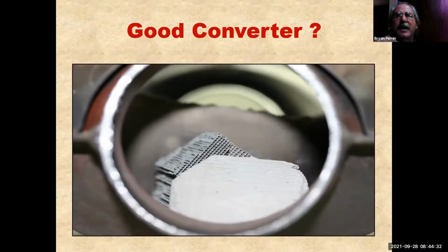And so when someone says, I tested something, that's why I routinely go, how did you test it? Well, I tested it. No. How did you test it? What methodology? How did you determine this? So when someone says, well, I tested it, it's good. Okay, how did you test it? Can the test you took only tell you if it's bad, like an ohm meter test? An ohm meter test can't tell me if something's good. It can only tell me if the windings are bad, not if they're good. There's a lot of tests like that in automotive that can't tell me if something's good, but unfortunately we're fooled into believing that if it passes the test, it must be good. No, it just hasn't failed.